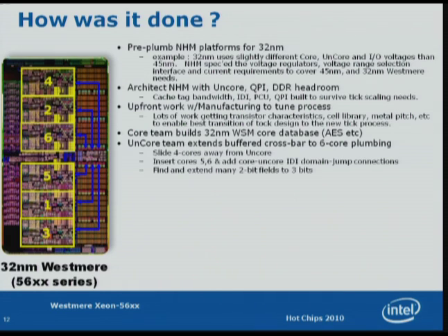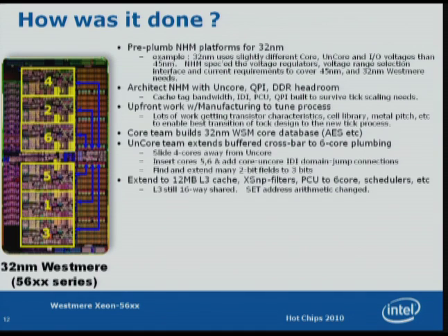Okay, so part of what was done here, again, this is the design team. You notice the cores 1, 3, 2, and 4 slid outwards. Why in the world did that happen versus tacking these 2 cores on the outside? That's design implementation issues. The designers had identified a means of saving effort, and when they put in repeater banks and things like that, they take a great deal of effort in the cache hierarchy. As we built this thing out, it worked out best to arrange the cores in this manner. Other than that, a lot of 2-bit fields needed to be moved to 3 bits, and that sort of good old-fashioned hard work. But it was fairly straightforward, actually, on this part because we had thought ahead on how to get here.